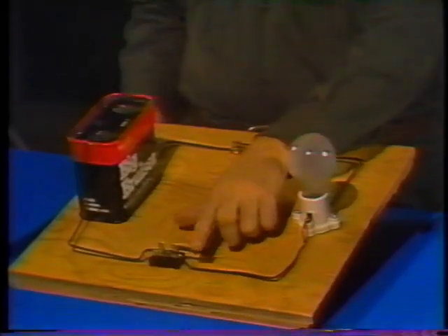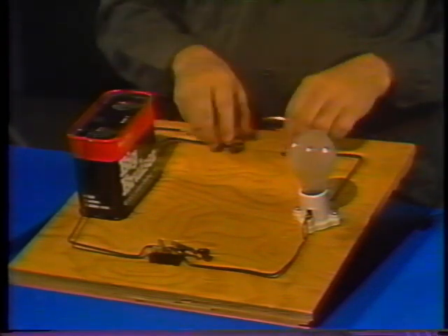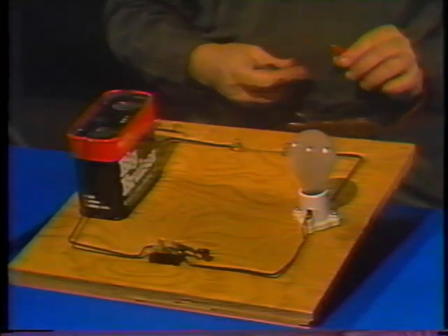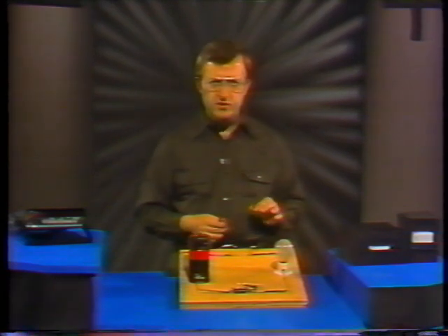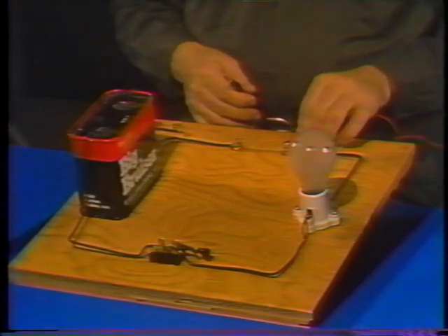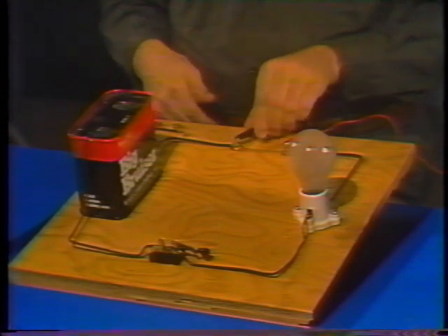We've used an ammeter before. Then we were only interested in whether the needle moved. But now we're going to find out how much current there is in this circuit. The switch is open, so we can disconnect this wire right here, remove those, and hook up the ammeter. You see, to use an ammeter, you've got to make it part of the circuit. The current you want to measure must pass through the meter. The positive lead goes on this side of the circuit, and the negative lead goes here.